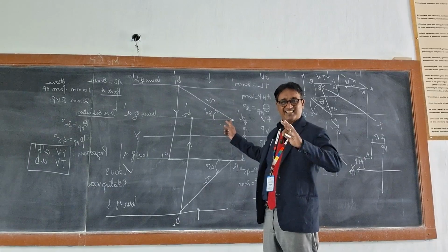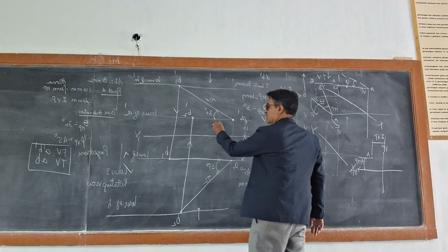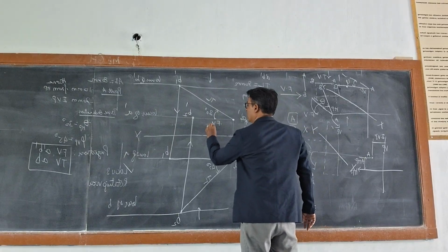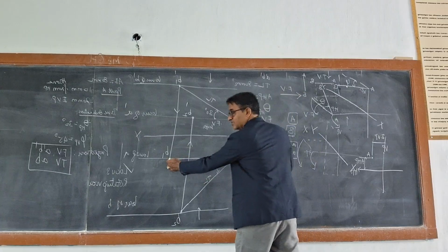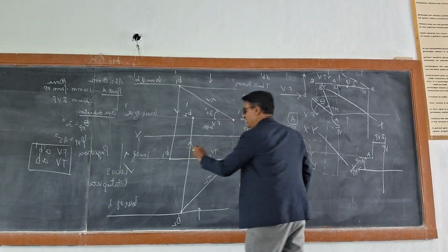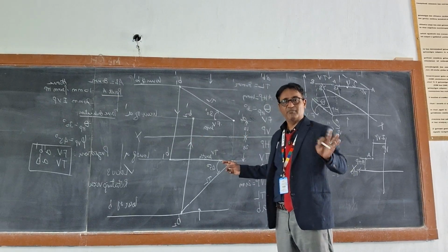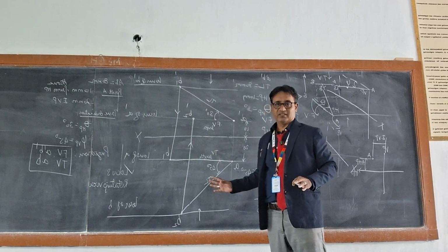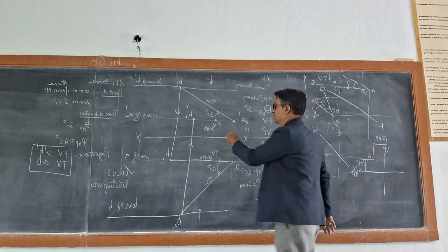Reduced length, which is nothing but the front view. So this is called the front view length. And what about this? This is called the top view length. You need not be confused because this is below XY. Therefore, anything below XY is the top view. Therefore, this length is the top view length. Similarly, above XY is front view. Therefore, this length is the front view length. Okay.